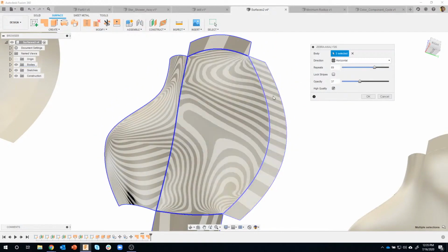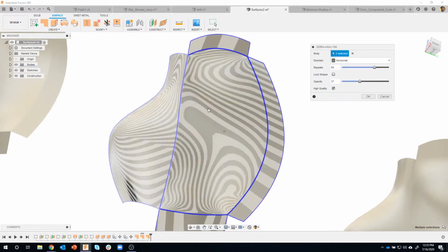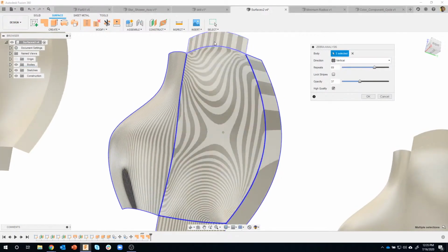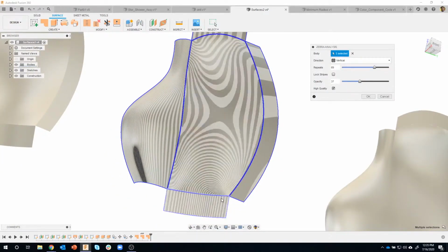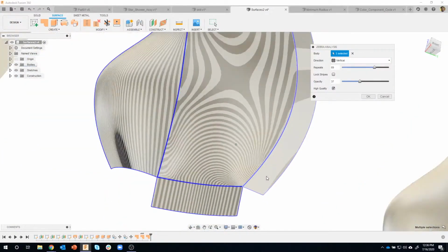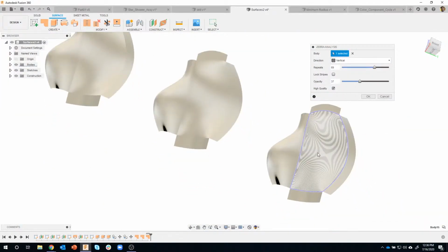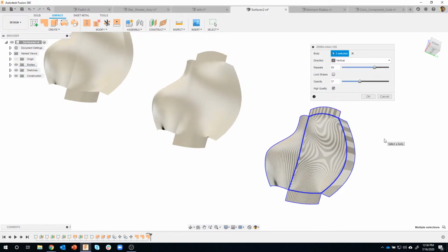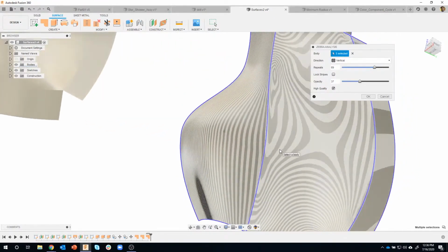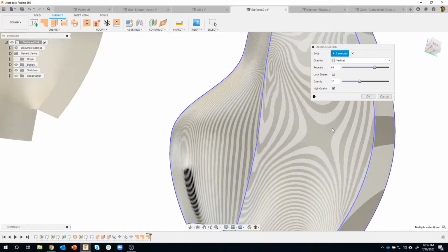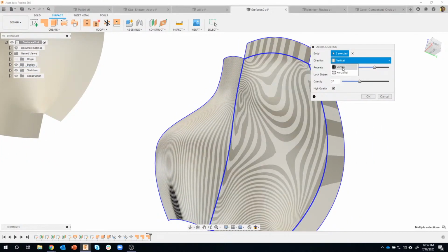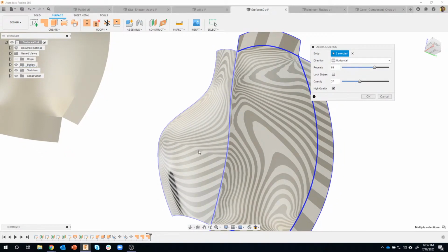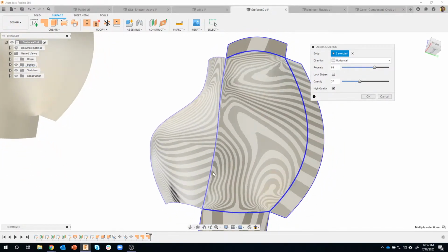But this is good. We're seeing all of the stripes touching other stripes. Let's go back to vertical in this case. We can kind of confirm that they look good at the top and the bottom also. We can see that those lines are touching. And then lastly, let's do the curvature one. So this was the tangent one. This is the one that was G2 continuity, and we can see that that looks really nice in that direction. Let's go ahead and do the horizontal, and you can kind of see it there. Again, that weird thing happens on this one, so definitely something weird with that surface.